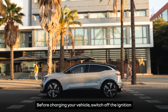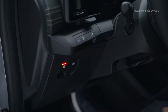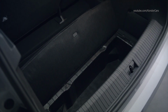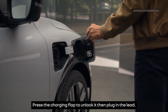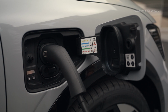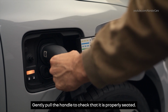Before charging your vehicle, switch off the ignition and be sure to apply the parking brake. Take the charging lead from the special compartment in the boot and connect it to the power source. Press the charging flap to unlock it, then plug in the lead. The charge indicator light flashes yellow to show that the vehicle and the connection are being checked. The lead automatically self-locks. Gently pull the handle to check that it is properly seated.